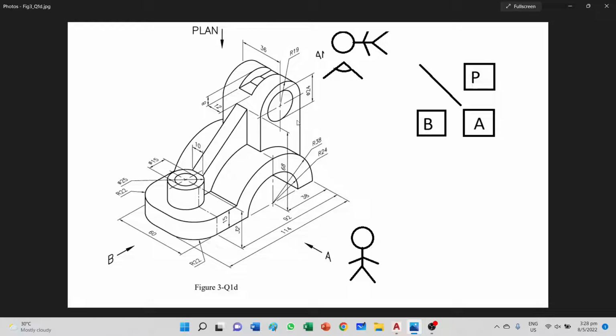And the width of this, what do you call that? Let's call it a tower. Okay, look at this. No, the correct term is a lug. L-U-G. What is the width of this lug over here? You know that the radius of the circle is 19, so the width of this would be 38, right? Because it's just 19 times 2, from this line to this line is 38.